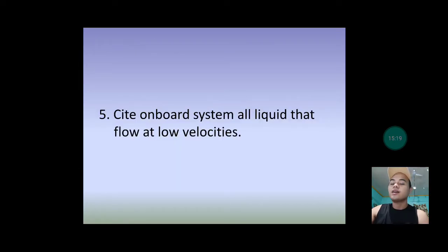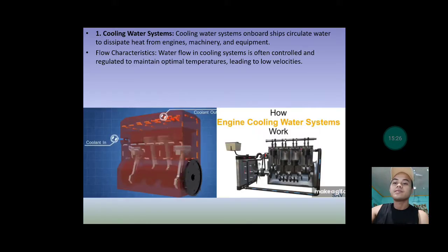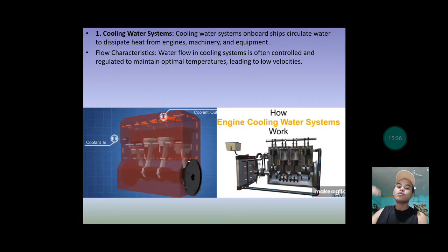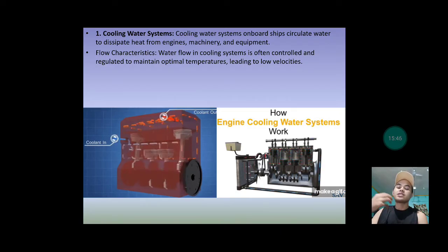Okay, so what are the systems on board in which we use low velocities? First, the cooling water system. It is very important to have low velocities for the cooling water system so that your cooling water will stay longer in the system, thereby increasing its heat absorbing capacity.